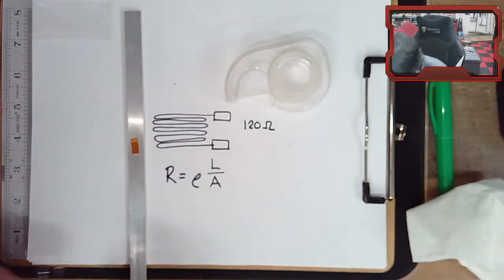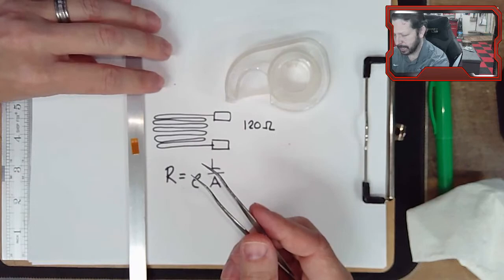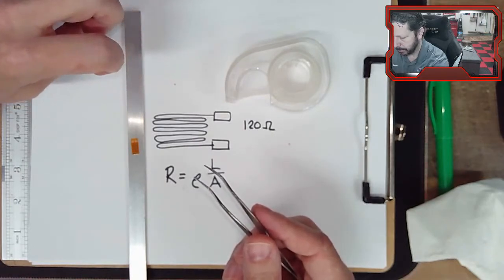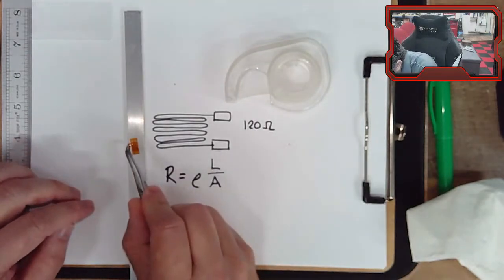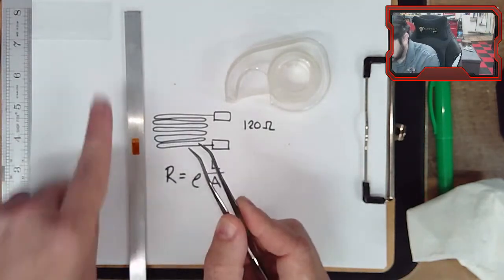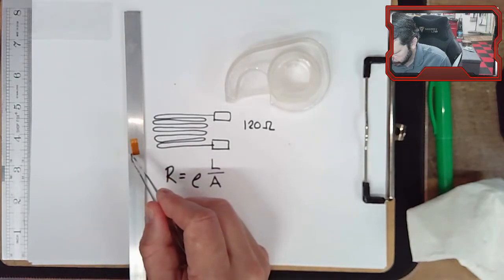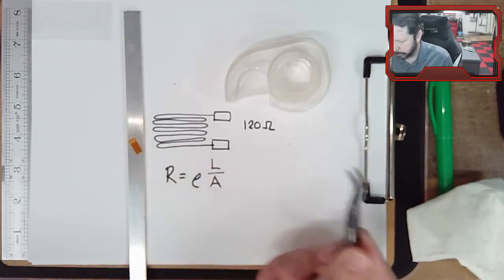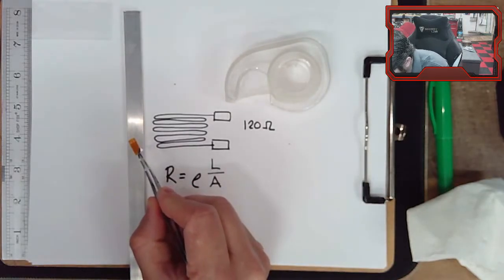The pad direction only matters because I'm going to have wires coming off of it, and I'm thinking of this side being the part that gets clamped down and the load is applied to the other side over here somewhere. In this case, we want it parallel. There are some instances where you have multiple strain gauges and you intentionally put them at 45-degree angles, but we're not doing that. We only have one strain gauge.